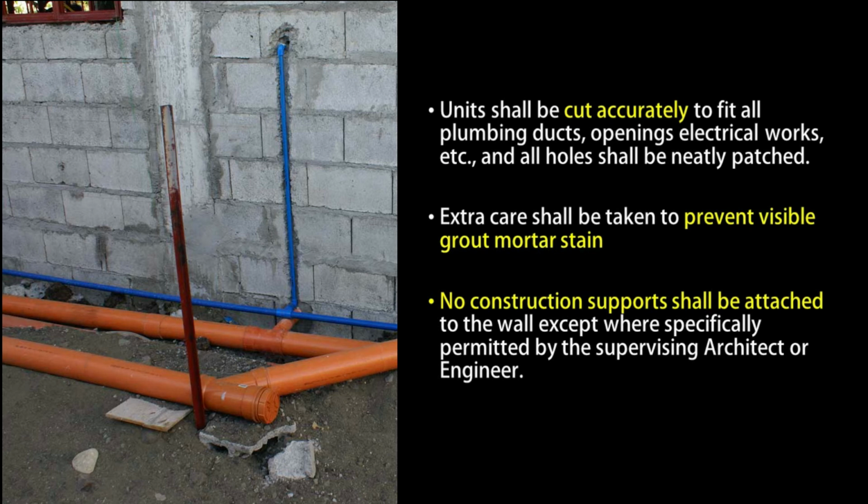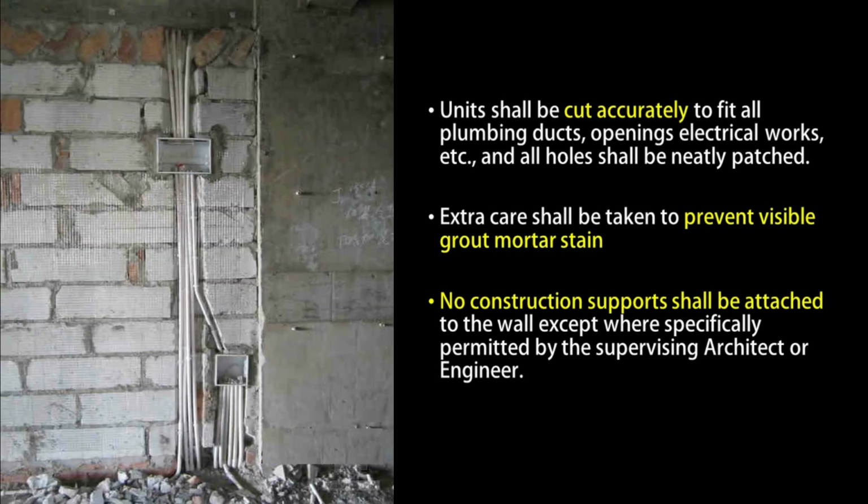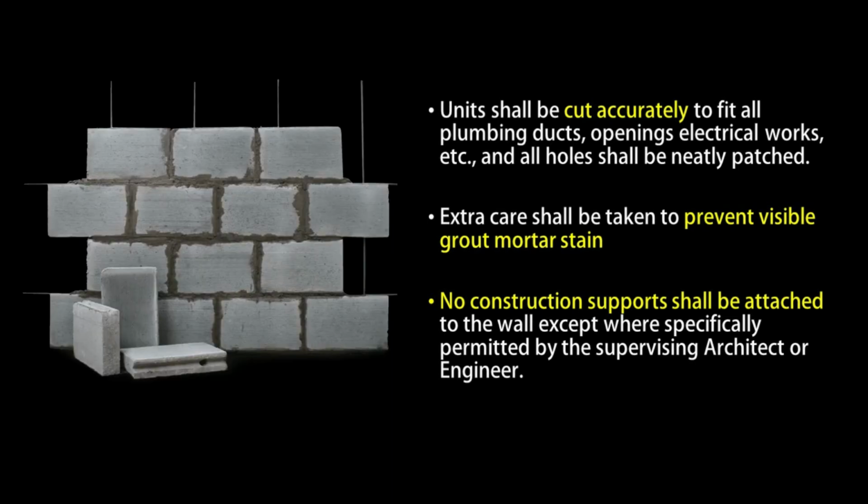Units shall be cut accurately to fit all plumbing ducts, openings, electrical works, etc., and all holes shall be neatly patched. Extra care shall be taken to prevent visible grout and mortar stain. No construction support shall be attached to the wall except where specifically permitted by the supervising architect or engineer.